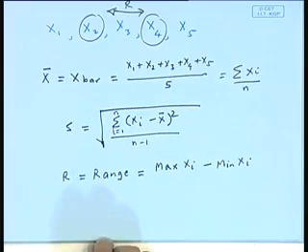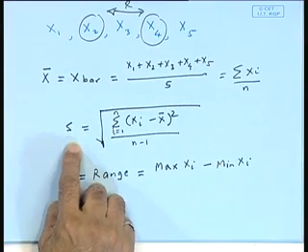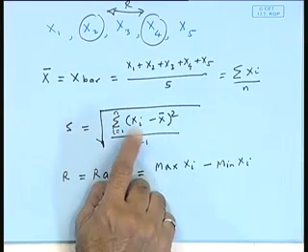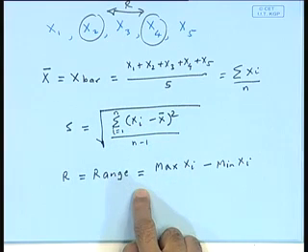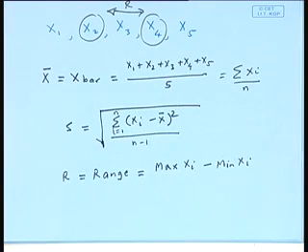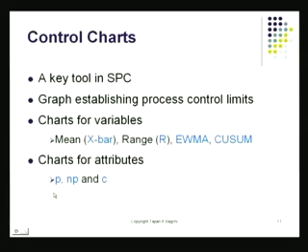That we'll be doing. Most of the time, I'll not have to use the standard deviation formula. One could do this, but it's a lot easier. If you're trying to do process control, then why don't you use the simpler one, which is the range chart. So I have here, if you see the screen there, the standard deviation chart, and the very next chart is going to be the range chart.